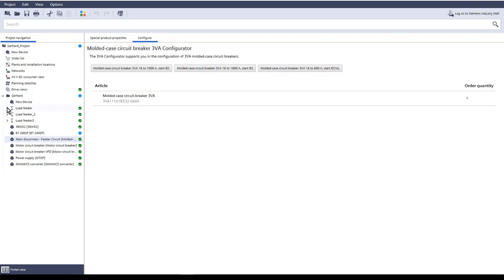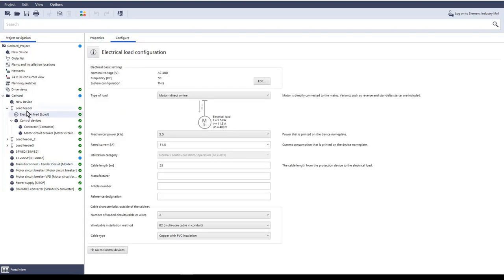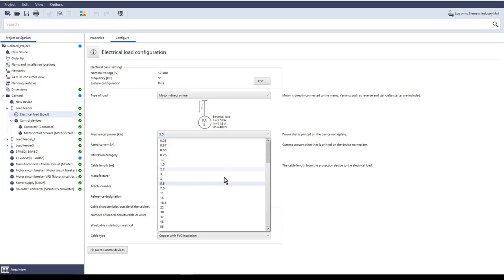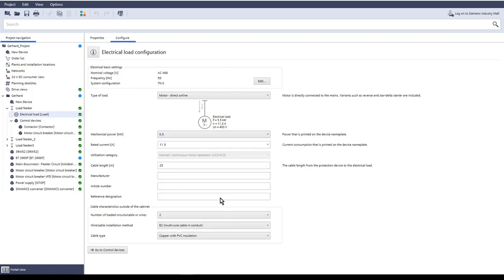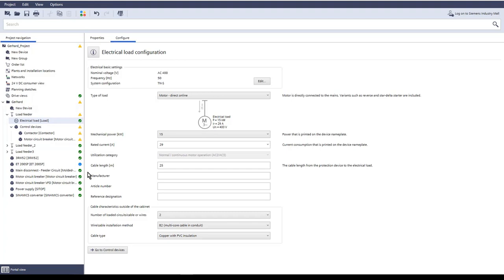I see that you also took into account the rotary switch. Yes, I did. Great. We can work with this. But you were mentioning some changes. What happened? Well, actually, three major changes. One motor needs to be sized differently concerning the power. At one motor branch, we need to significantly change the cable lengths to the motor, and you told me that this really matters. Yeah, totally. This will change the short circuit current calculation in the starter and the motor. And one starter for one motor branch needs to be changed from direct starter to reverse starter. Can you implement this?